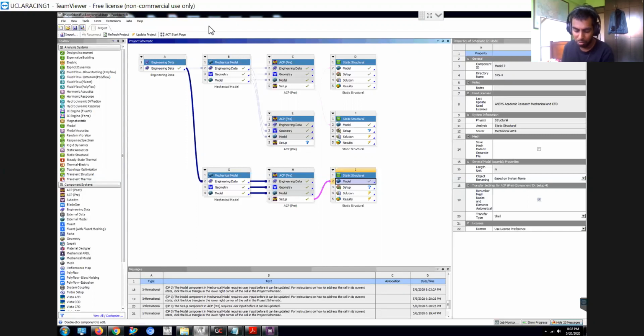The knockdown factor comes into play with carbon fiber because of manufacturing defects. For example, someone messed up the fiber orientation by a few degrees, and because of that you don't know what's going to happen. Or a random piece of material like peel ply got stuck in the middle of the carbon fiber, or a random void appeared while laying up. Because of all of this, you should aim for a factor of safety of 2.5 at least. So those are the two things you usually have to think about: deformation and factor of safety.